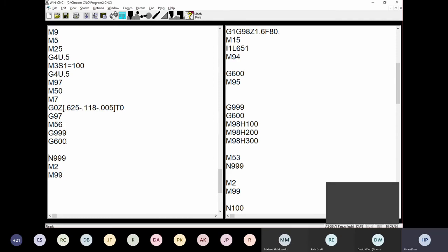But one thing I want to say about G600 is, when you call the tool in the back spindle, remember we're using the left hand cutoff tool. If you're using the left hand cutoff tool after cutoff, that means the material is still sticking out further or something.